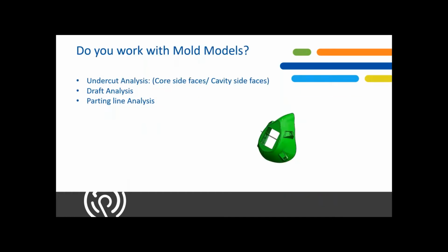All right, and lastly, if you work with molds, these are great tools that you should be using to help you evaluate your molds. So there are undercut analysis, there are draft analysis, and there's also a parting line analysis. And I'm going to make sure that I go through all of this today.